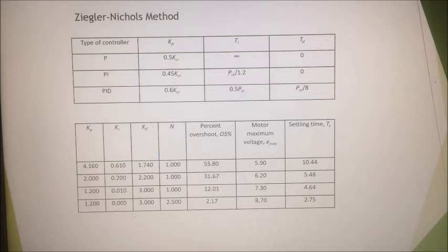For this system, the desired criteria of the control design are that the trolley can track the reference input, while the sway of the pendulum is quickly dampened. Also, the input voltage should not exceed its maximum value. Therefore, in order to deal with this, I prefer the Ziegler-Nichols method in this case, to help me obtain certain values of PID, so that I can get the best design parameters.